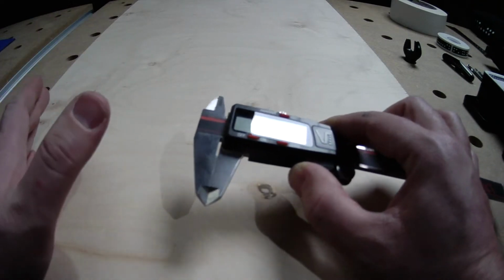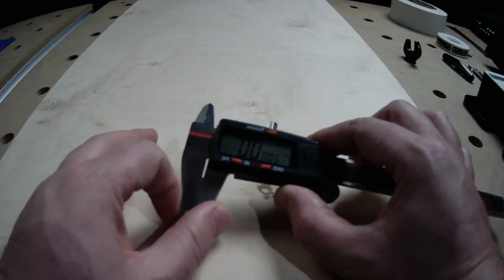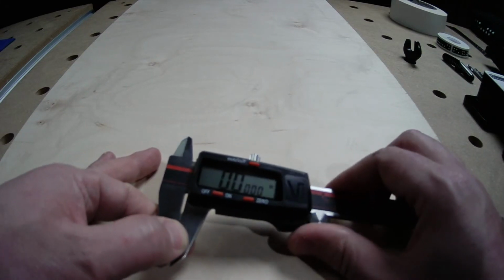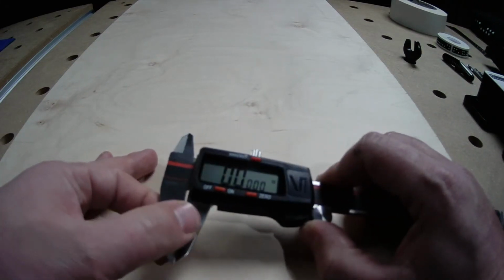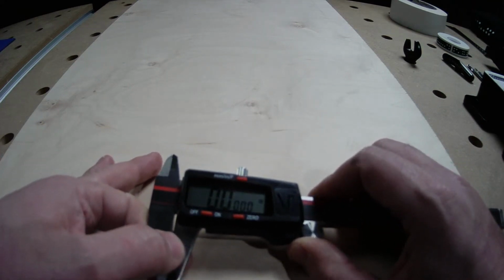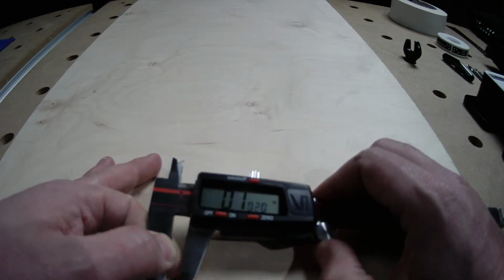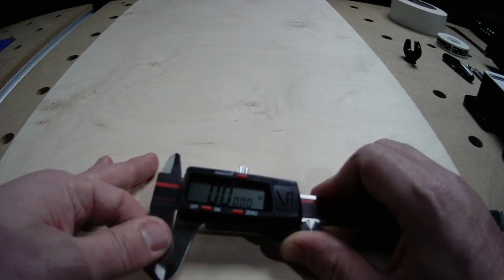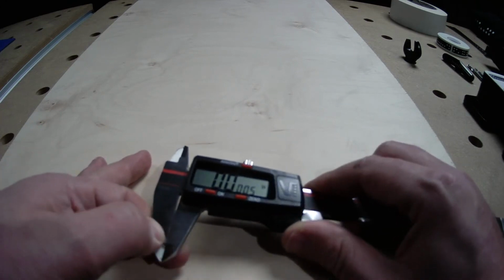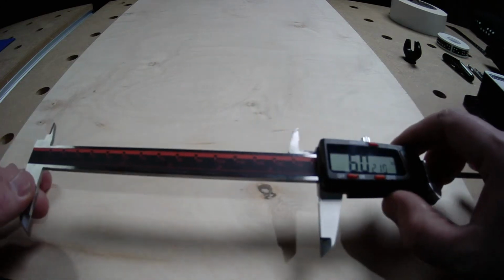Just for laziness, I tend to like the digital calipers, and like I said, the starting price is quite inexpensive at this point, or you can go all out and get some really fancy machinist ones, but it's really not necessary for woodworking. Or if you're a dial caliper kind of person, that's also great. You really just want to be able to know, down in the thousandths of an inch territory, ten-thousandths of an inch territory, where things are in the real world, because we are working at those levels of precision, and a tape measure really can't get you there. So calipers are great. These are just a standard 6-inch set.